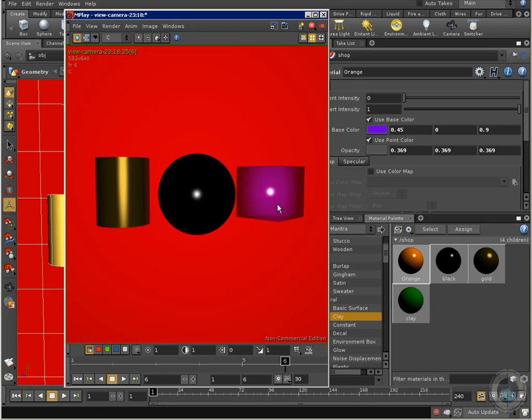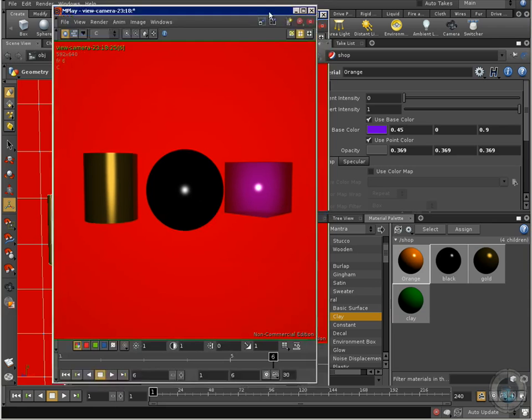Now, we probably can have a better idea of this if we place some lights, but other thing that I want to show you is that we need the alpha channel for these kind of materials when we want to create some kind of glass or windows, water, different materials, and also because when we composite our 3D objects with actual footage, we can use the alpha channel in order to remove the unwanted areas of our scenes. In this case, the red. Okay, but actually the red is not an alpha channel.